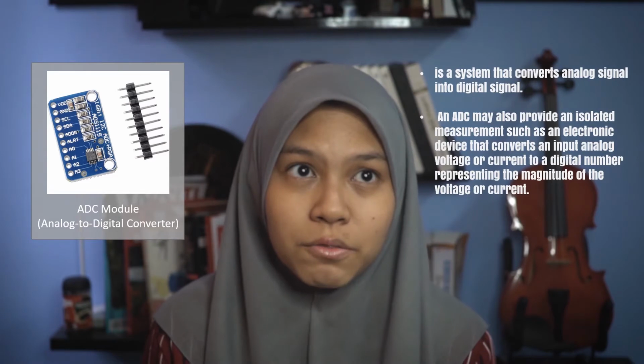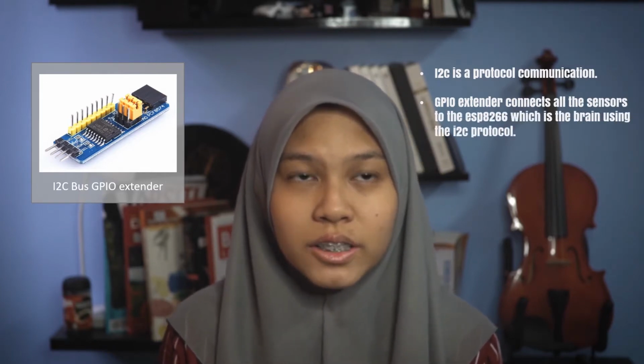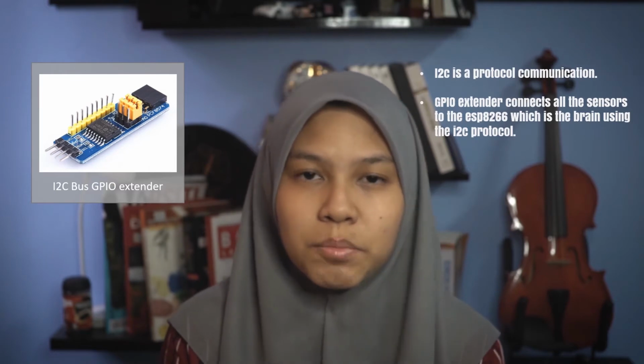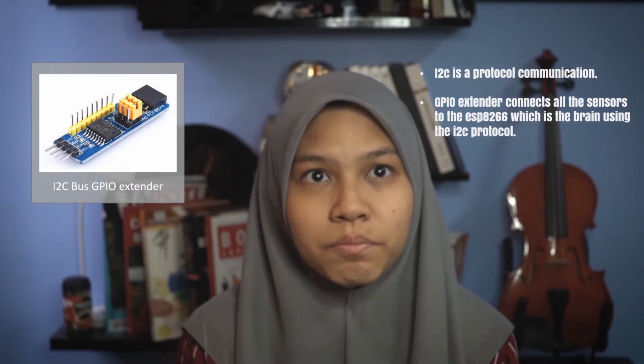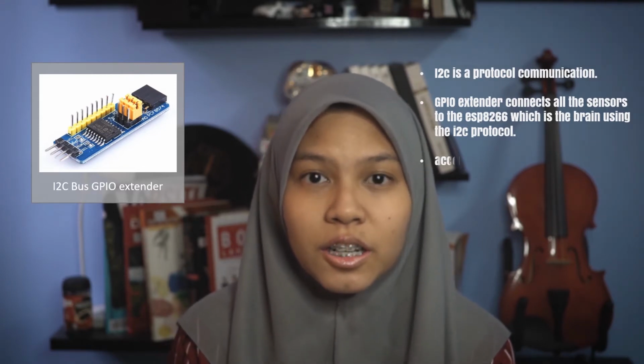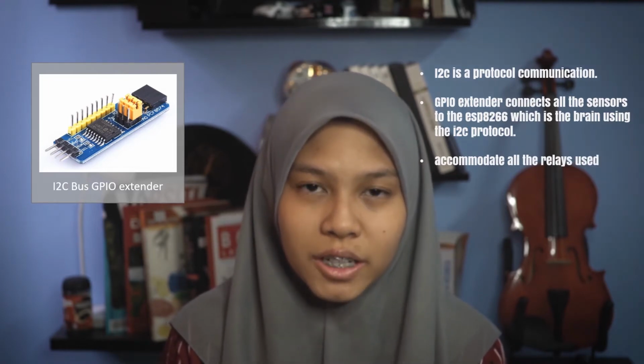For the next one, we use the I2C bus GPIO Extender. I2C is a communication protocol, and what the GPIO Extender basically does is connect all the sensors we are using to the ESP8266, which is the brain, using the I2C protocol. And the reason we are using all these GPIO Extenders is to accommodate all the relays used for this project, which is a total of 9 relays that are responsible for controlling the car mechanism.